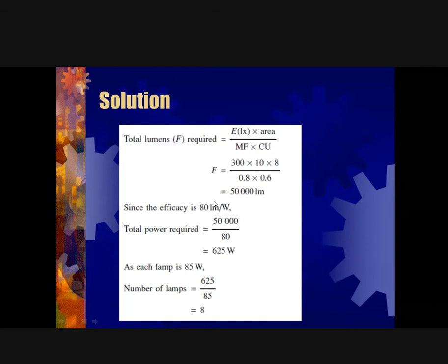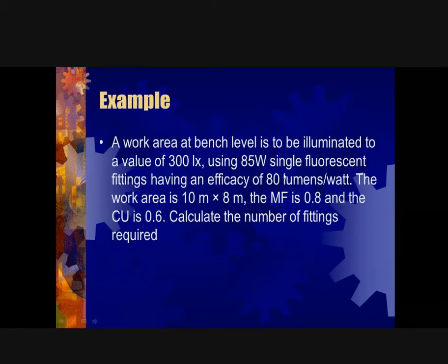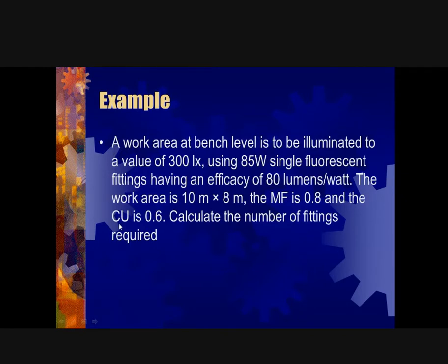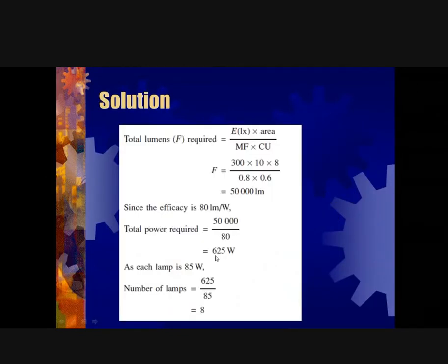If we were given a different type of lamp, we'll realize that it will also change the number of lamps that we need. So before we do our lighting requirements, it's always best to use the typical lighting requirements for a particular area, which is the amount of lux. And then based on the amount of lux, we can determine the particular lamps. So we must have an idea.